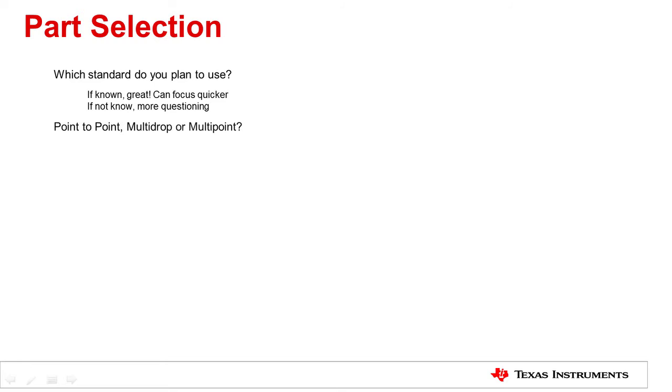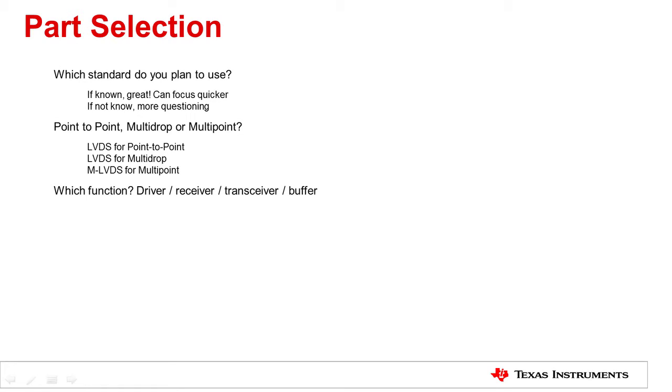If not, the next question is what topology will be used. LVDS can be used for both point-to-point and multi-drop applications. However, MLVDS needs to be used for multipoint applications. After selecting the standard, device functions and channel numbers should be considered.